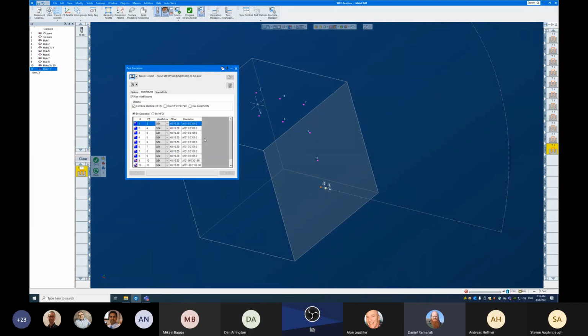And because there were too many work fixtures, the post has specified a fallback behavior. In this case, it has chosen to fall back to D style. So it couldn't give each operation its own. It only has G54 through G60, and there are 11 operations here. So it has 7 work fixtures. It has 11 operations. It's not going to work even with the ones that are being combined. So it's chosen to go back to G54.